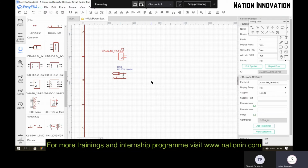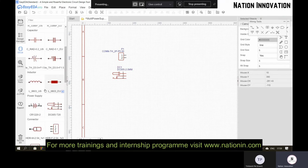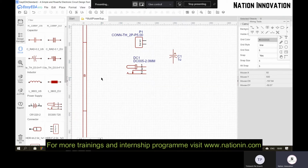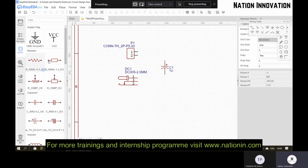And to filter the noise coming from this power supply, we will connect a capacitor, that is electrolytic capacitor. So make sure that your capacitor is a through hole capacitor and rotate it so that the positive terminal is connected to the first pin of whatever power supply you are going to provide. And to this DC power supply, we are going to connect a LED to check whether our input is coming or not.